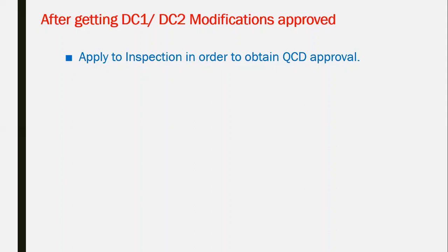Wherever there are fire extinguishers, there should be a title and directional text showing the fire extinguishers, and they should be accessible. They check all the accessibility within the building and the escape routing, and that it is free from any obstruction of furniture or equipment, etc. The same as what we discussed in the NFPA 101 section when we talked about egress routing. So they are going to check all of these documents, and after that they will give you either approval for the building or they will send comments.